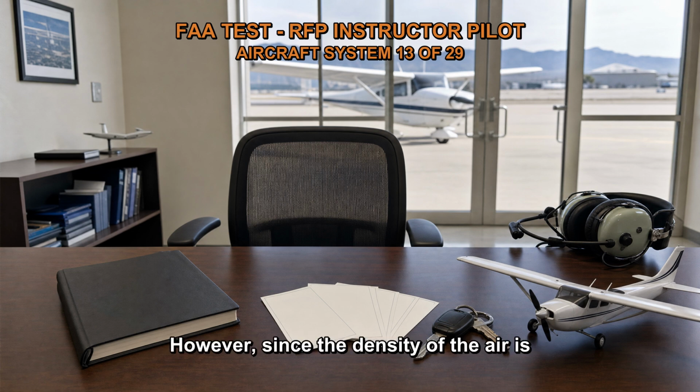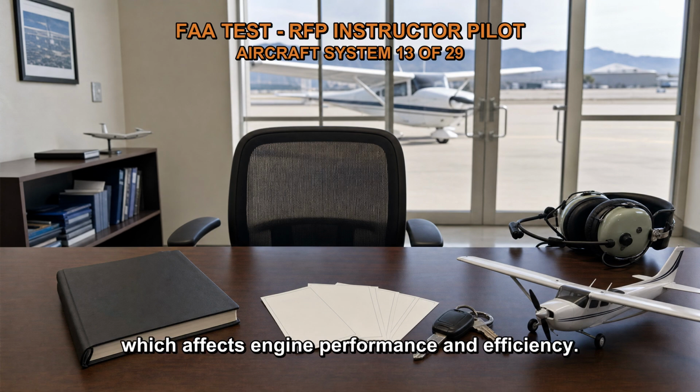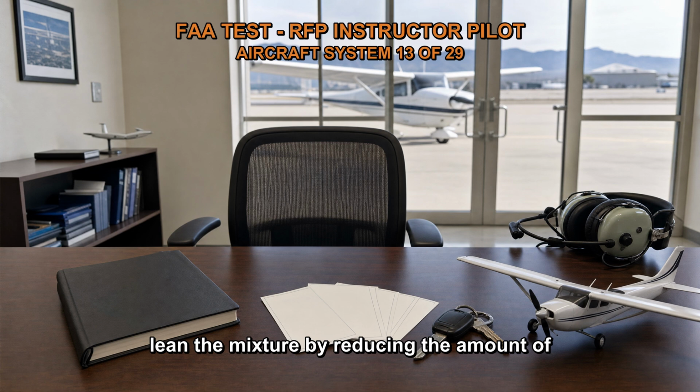However, since the density of the air is decreasing with altitude, the fuel-to-air ratio becomes richer, as there is less air available for combustion. This can lead to an overly rich mixture, which affects engine performance and efficiency. To maintain the proper fuel-to-air ratio and optimize engine performance at higher altitudes, pilots need to lean the mixture by reducing the amount of fuel supplied to the engine.